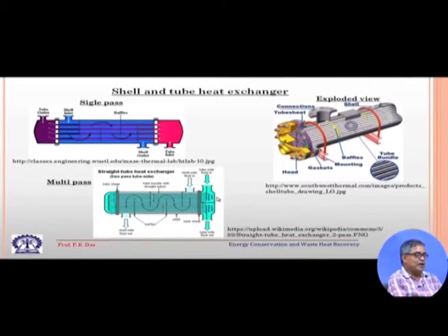So, you see a fluid particle starting from here to here has to traverse the total shell length 2 times. It will have more opportunity to be in contact, of course indirectly, with the shell side fluid, and we will have a good amount of heat exchange. So, this is one arrangement where I have shown a 2 pass arrangement.